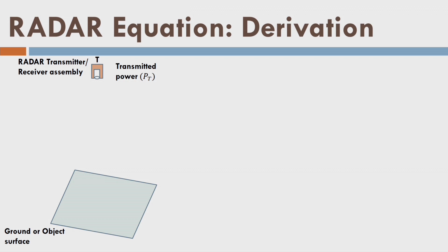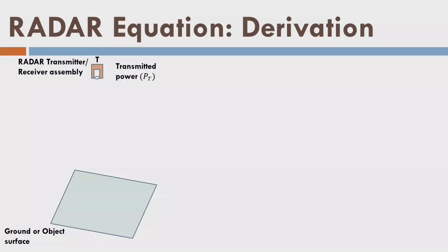In the case of the geometric aspects in the last lecture, we have assumed that we are getting some responses, what we call impulse response, and based on that impulse response we have defined the impulse response width, resolution, the pixel and so on. If the impulse response is more than 50% of the transmitted signal, then we will accept that impulse response as a reflected backscatter. The question is how to decide that, or how the radar sensor or receiver measures this impulse response. Let us see, there is a radar transmitter receiver assembly.